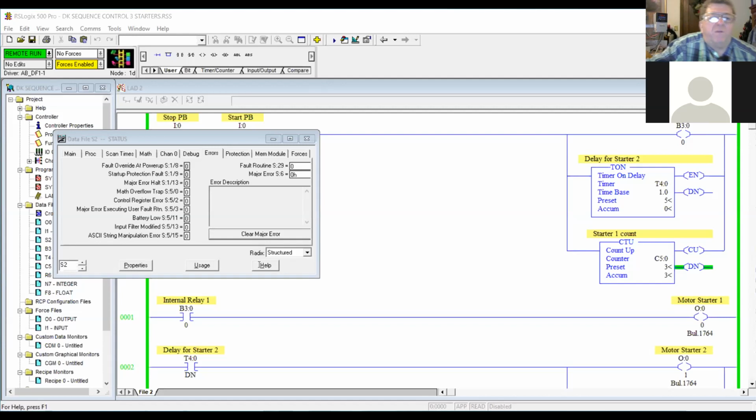Yeah. So for the error codes, an error code of 001, a default program was loaded. A non-user error occurs. If your memory is corrupt, it would be a fault code 3. A memory module hardware fault will be a code 6. A code B would be a base hardware faulted or incompatible with operating system.